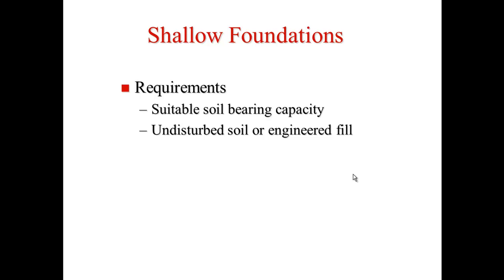Shallow foundations require suitable soil bearing capacity, undisturbed soil or engineered fill. And this is kind of important because if you excavate for a foundation, you never want to dig lower than what you need to, because undisturbed soil has the best bearing capacity as opposed to backfill.